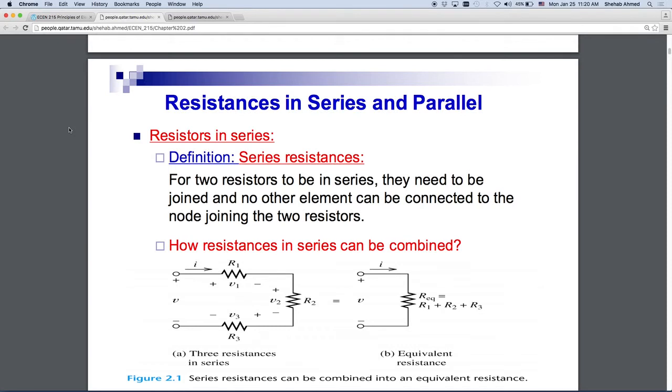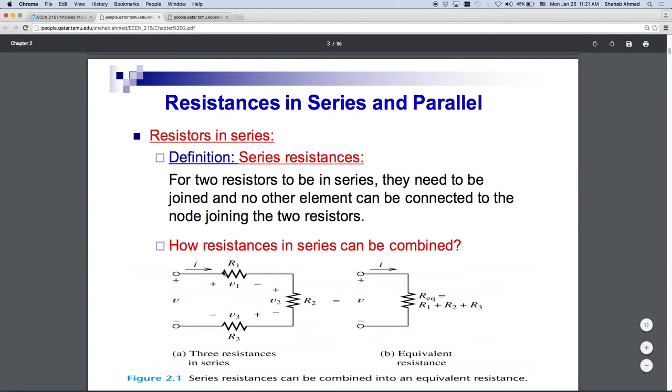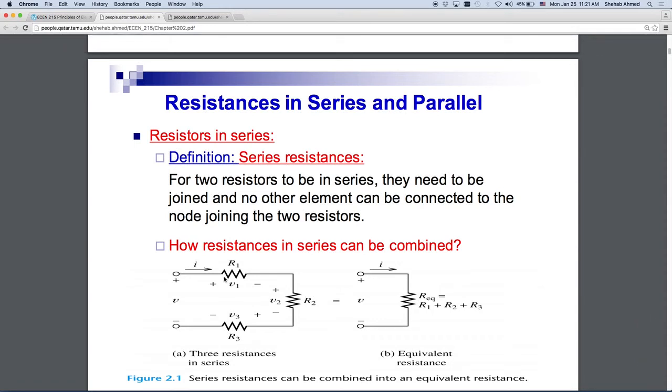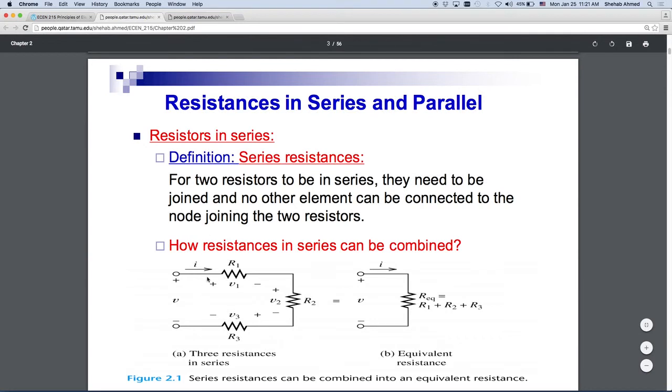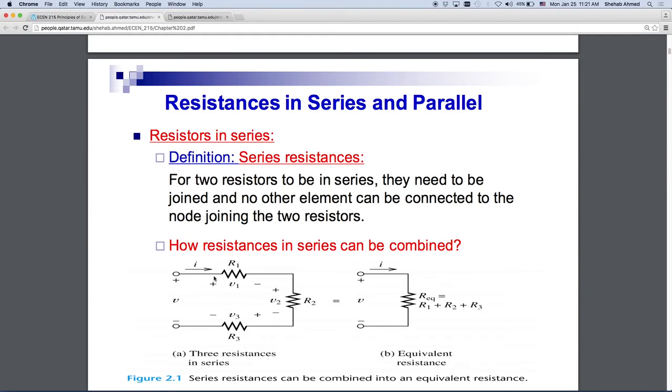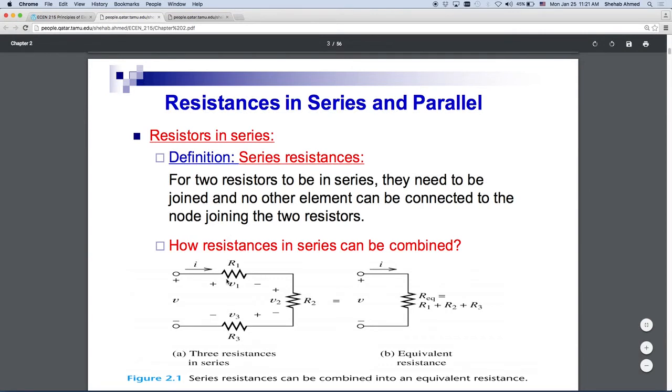So for example, we have the series connection of resistors. You have a flow line with many different restrictions, multiple restrictions in series, right? All of these restrictions are causing pressure drops, requiring you to increase the pump pressure to be able to maintain a certain flow rate, right? So the resistors in series are summing up, they're adding up to each other, increasing the resistance to flow, and you would have to sum up these pressure drops to be able to compensate them. So the idea of resistors in series is the same.